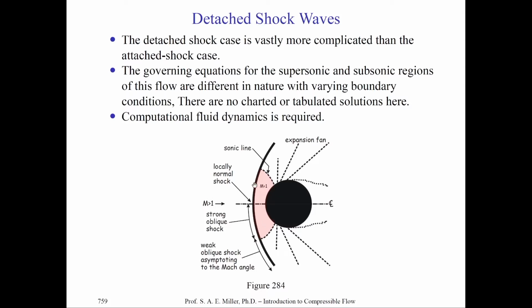And of course, behind the relatively strong shock and part of the weak shock front, depending on its local Mach number and wave angle, we'll have a subsonic condition behind the shock. Outside that region, we have supersonic flow, which is represented as indeed an expansion. And behind the cylinder, we have a turbulent wake. It is indeed a very beautiful flow.